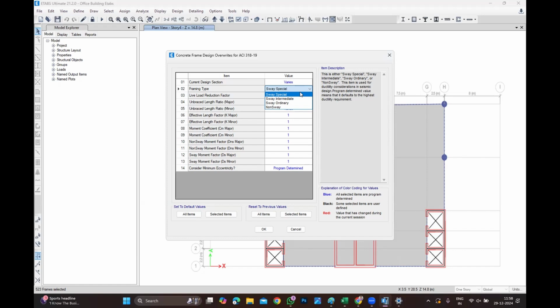Somehow it is a bit clearer now. For a G+1 building, you don't need to consider seismic. But before, it was not. You approach a different engineer, you get a different opinion. For villas, consider seismic. Why? Nobody has an answer. Wind makes sense, because wind you cannot avoid. Wind is usual. Seismic is going to come once in a blue moon. So why should I increase the cost?